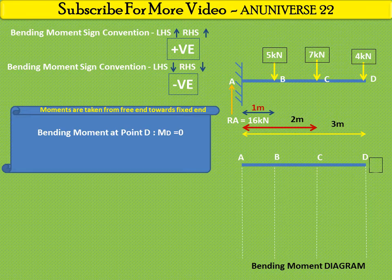Now we calculate the bending moment at point C. For this we move from D to C, and the distance between D and C is 1 meter. So the bending moment at point C is equal to 4 into 1, that is 4 kilonewton meter.